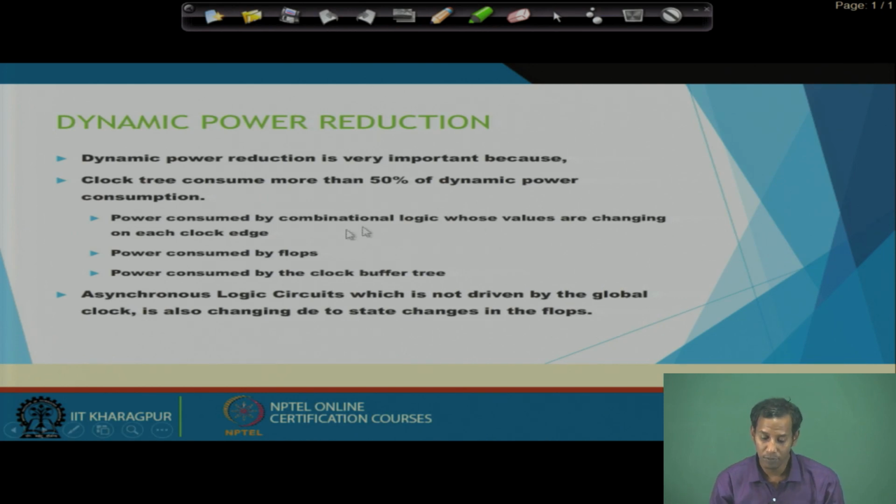And then there is the combinational logic. Whenever the inputs are available at the input end, the output immediately changes its behavior. Depending on the logic, the output state changes, which again creates very fast switching in combinational circuits. Whereas flip flops have to wait for the clock.